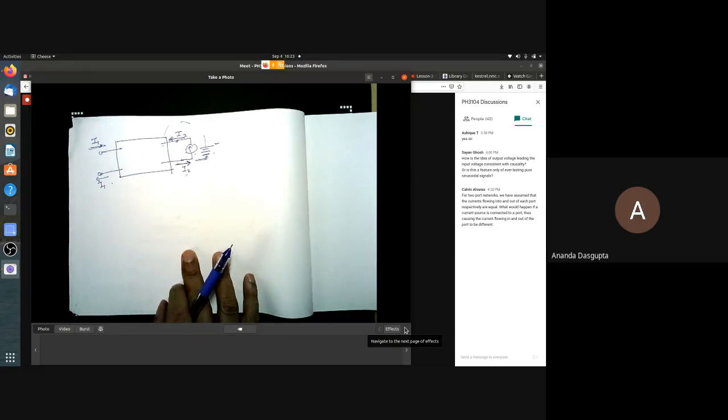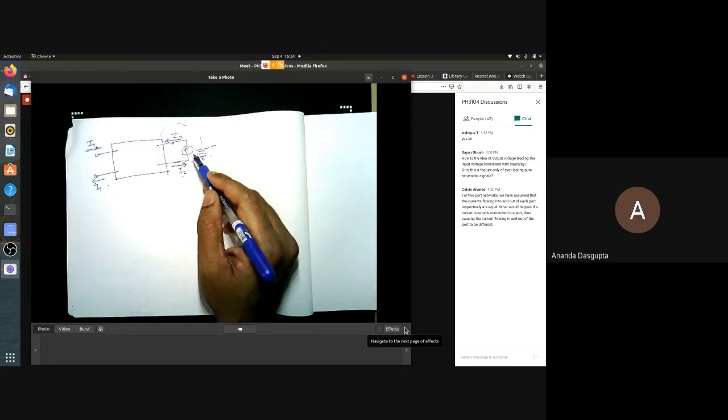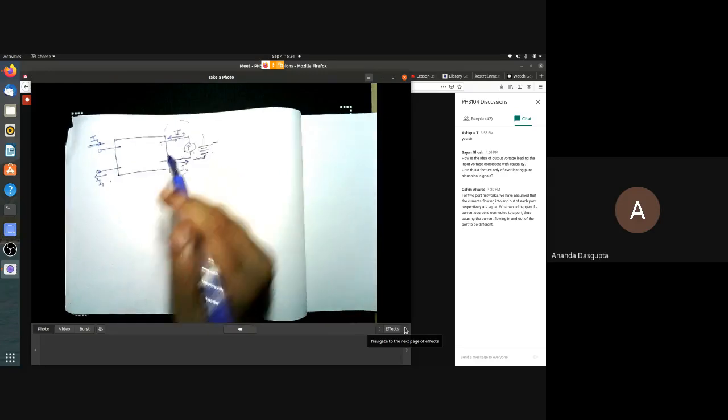For a real battery, there are other processes which decrease the voltage with increasing current and so on, which is why a real voltage source is always modeled with an ideal voltage source in series with a resistance. That's just a Thevenin equivalent. Similarly, a current source is always modeled with an ideal current source in parallel with an admittance. Right?